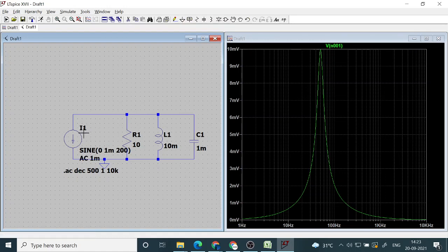When you inject a current, this is a constant current source, meaning an AC ideal current source. So the value of current is entirely decided by the source itself, but the voltage is variable. That will be determined by the current that we are injecting into the node and the impedance offered by each of these components. There are 3 components in parallel.